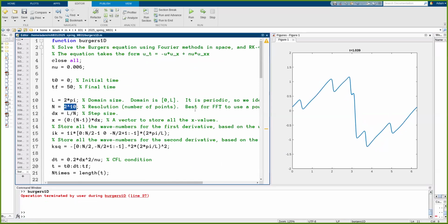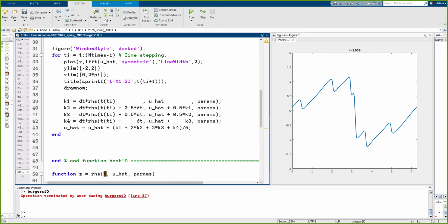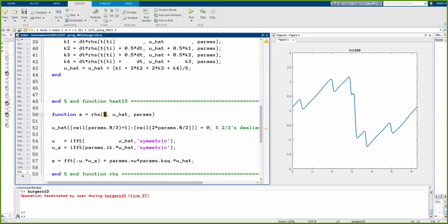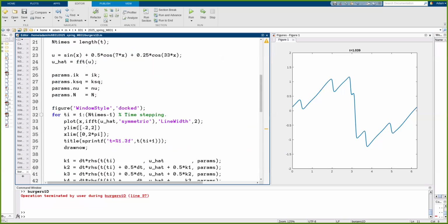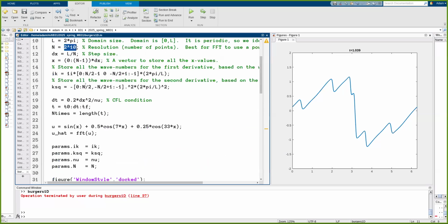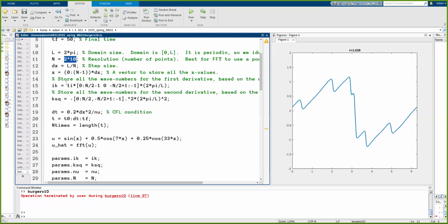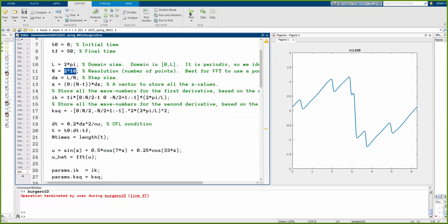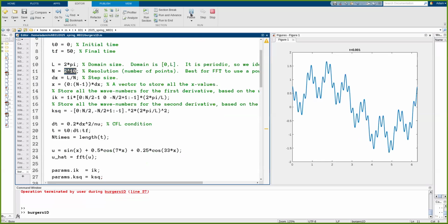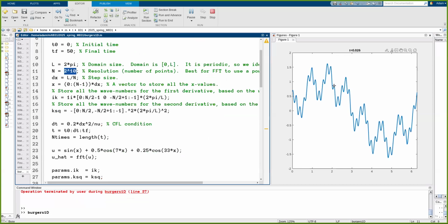In space. So every time through this operation, we're doing 4 Runge-Kutta stages. So that's something like 4,000 of these operations. Each one involves 3 Fourier transforms. So this is now involving many different Fourier transforms going on through these steps, and that's multiplied across the various time steps. So this thing is getting pretty expensive, and it's going to run a bit slower.